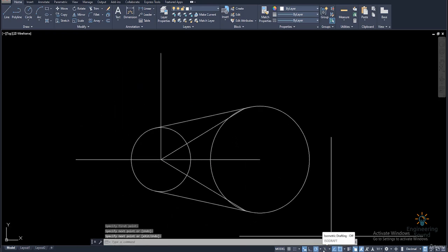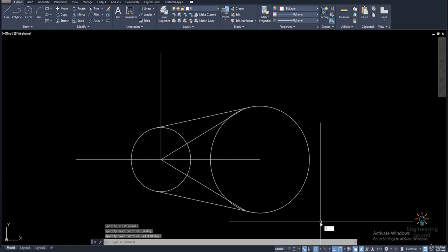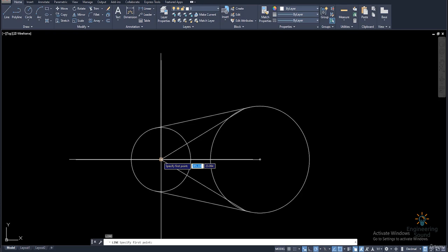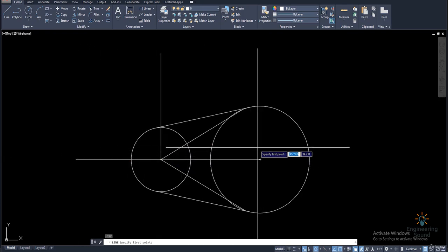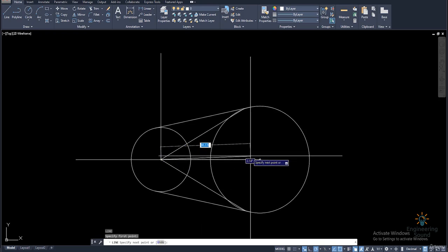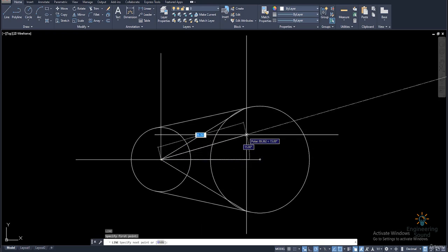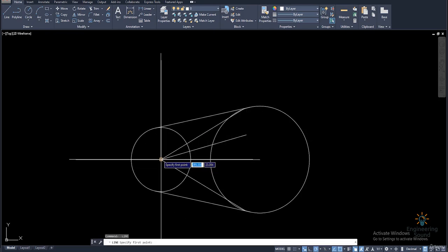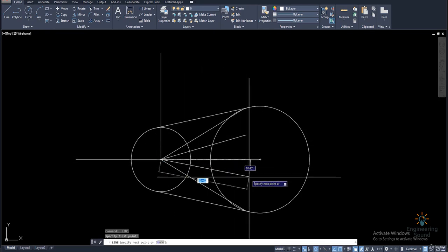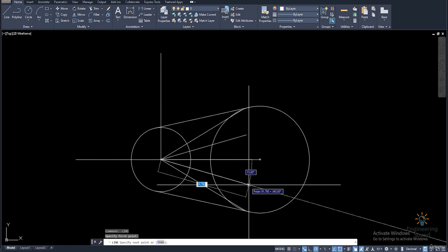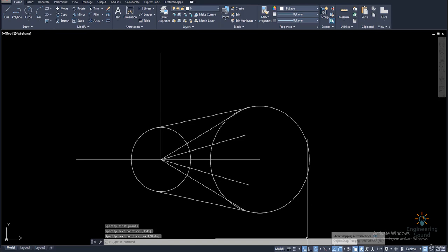And if I'm going to use it on 15 line, and I select 15, it will give you the 15 line. Okay, click here, and you can see that it's giving us a tracking line on 15. So you can easily draw the line from here as per your required angle. Okay, enter, you can see it. So that's how you can use your polar tracking from here.